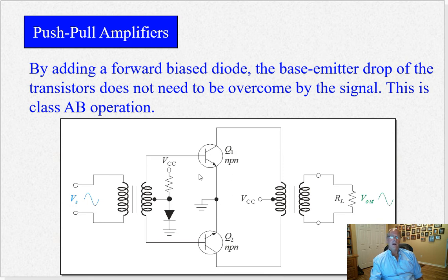And in fact, in a Class AB, this is called Class AB operation, when they're biased up like this and almost turned on, these are all matched silicon on the same substrate. So basically cut out of the same piece of silicon. So they match. This fixes the crossover distortion problem, the Class AB circuit. You don't need a transformer to do this.